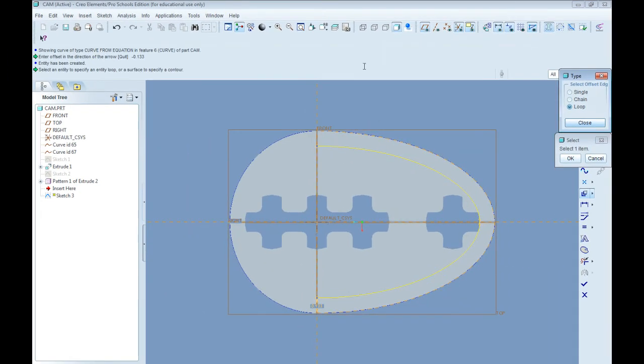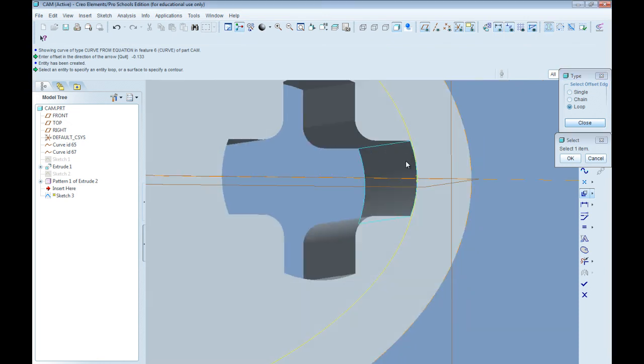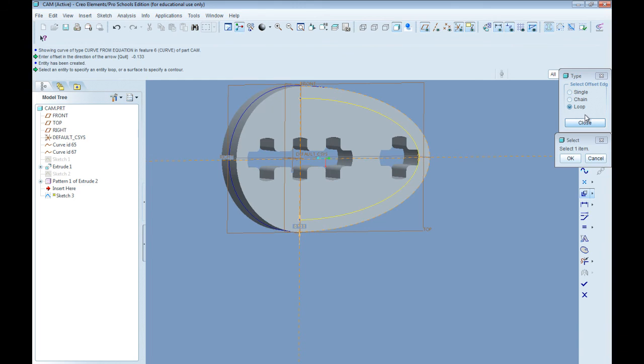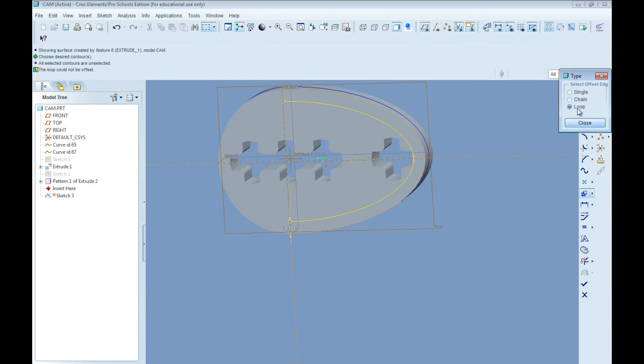So that number comes from, if you zoom in, you can see that this line is coincident with the diameter, or the side of this surface here. So I think when I measured this, that's what the unit was in the part. So I'll go back, create another loop around the surface. Put here a single, and then negative 0.133. So these should still be coincident. Close this.